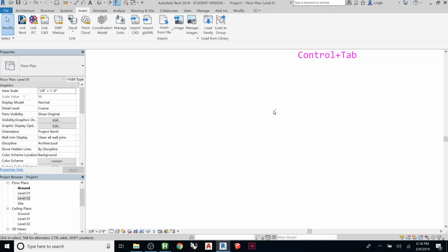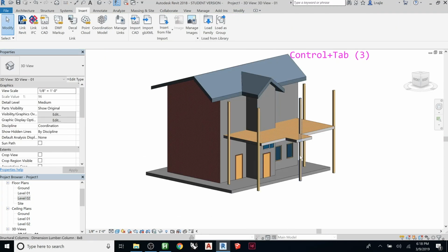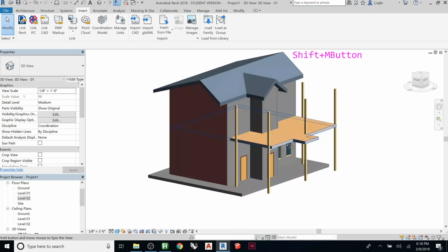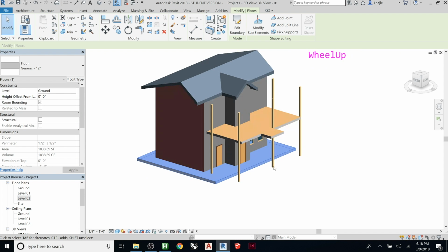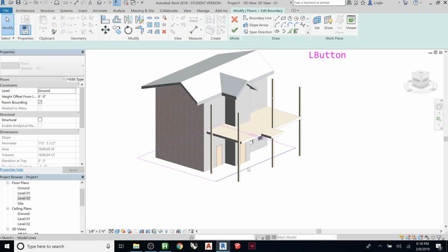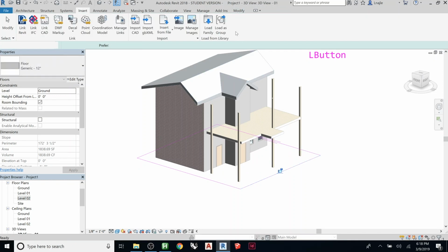And then now when we go to our 3D view, you'll see I made the floor go way out there. We can move the windows out, we can move the walls with it. There's tons of stuff you can change here. Let's modify this. Here's a cool one. You can also edit the floor in the 3D view. So here I'm going to try and grab that front face, but Revit doesn't know what I'm trying to grab. So I'm going to hit tab until I see it highlight. There it is. I'm going to click now and click there, and it will bring it out.